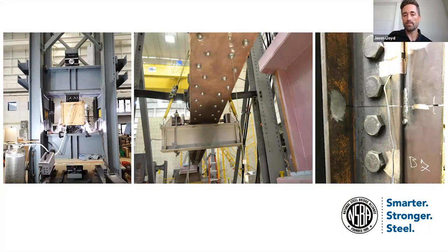Of the 20 specimens that were fractured, only one actually fractured at that stage. In all other cases, we had to implement a crack opening displacement at the notch using hydraulic wedges in order to initiate the brittle fracture propagation. I mean, it really was very challenging to do. These things were really difficult to get to break.